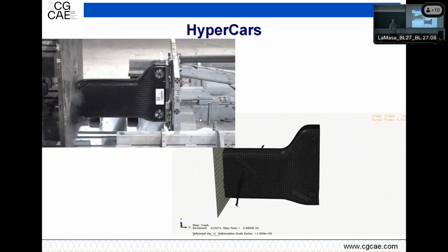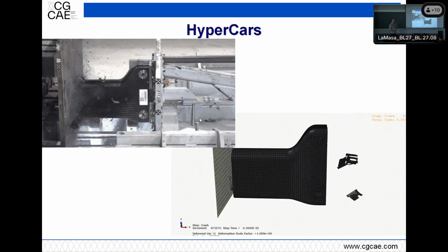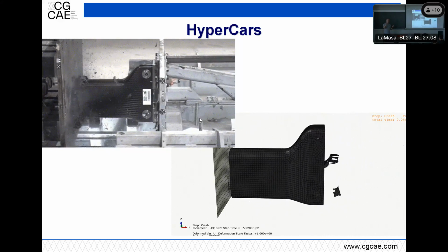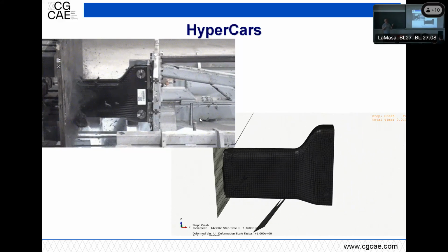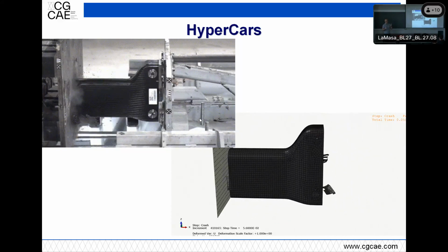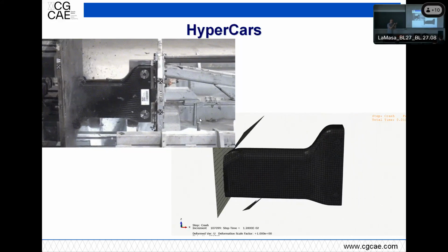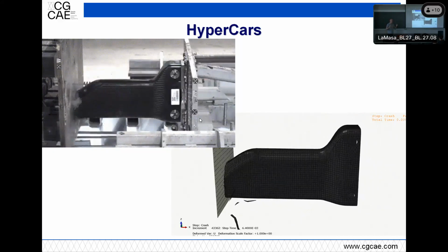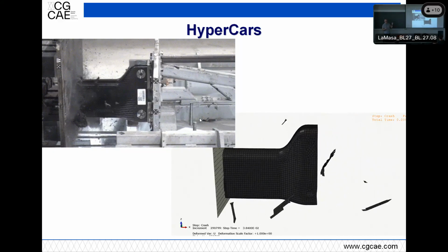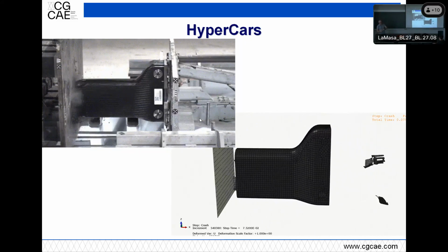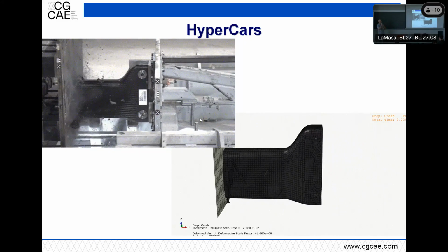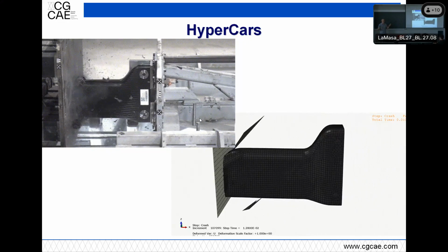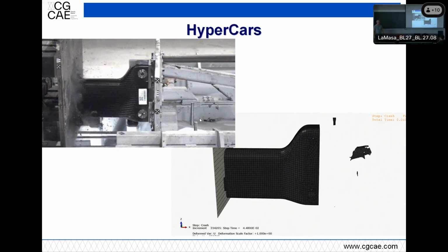And then it runs iterations, checking for the strain energy, and where it finds a low level of strain energy, it changes the, how do you call it, the stiffness density. So it reduces the Young modulus of those elements to a very low level. So the elements are still there, but they contribute less to the next iterations. So sometimes some of the elements that got low density at the beginning come up again. And you can check all the iterations it does, and you can see how it's developing.